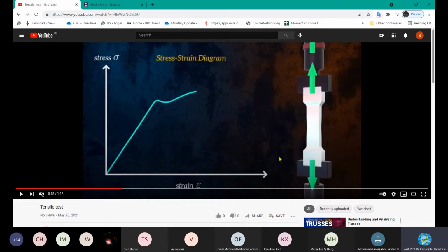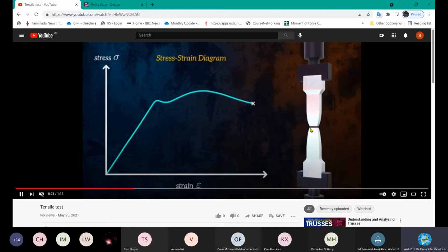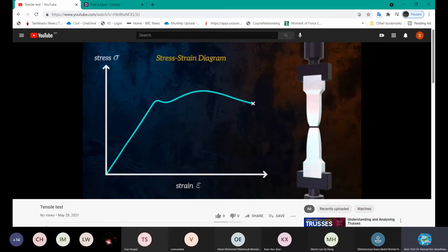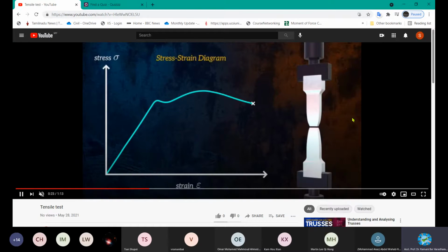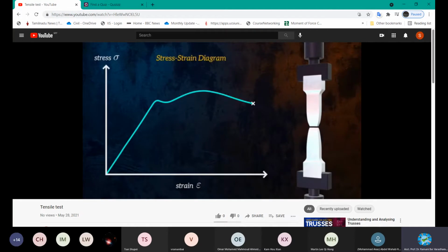Hope you can see my cursor moving. Necking started. I see the necking. Necking started growing in this dimension. In addition to the elongation, the necking is also happening at one point. Broken already. Breaking point. It reached the breaking point. This is how they test materials, whatever it may be. Maybe they come out with an innovative material. They still have to undergo a tensile test like this by pulling at the ends, applying the load, and then you can plot it. Come on, let's understand from this